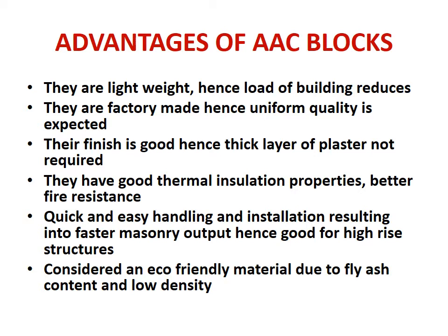They have good thermal insulation properties, better fire resistance, and they are quick and easy to handle. They are quick for installation also because of the size. So that results in faster masonry output, and it's good for high rise structures because they are light and they are quick in handling and also quick in installation. Then they are considered, as I told, eco-friendly material due to fly ash content and low density.